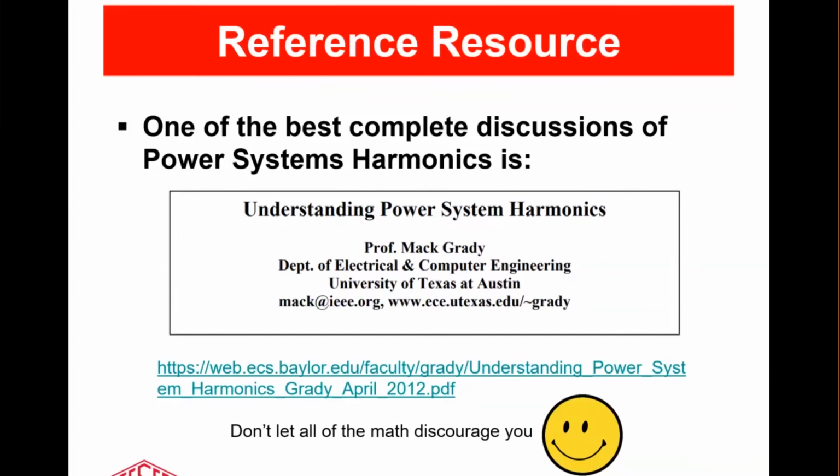And so the big initial cost there is that the size of the infrastructure that you have to install may have to be several times larger to serve a customer with a highly harmonic load than a customer with a more reasonable load. So that's the really big issue.